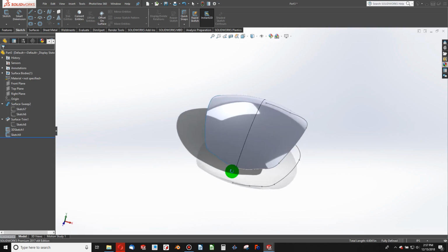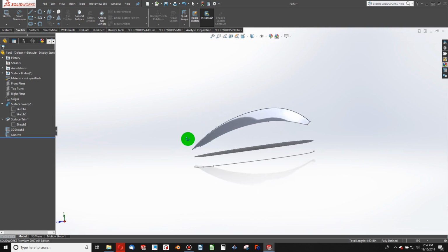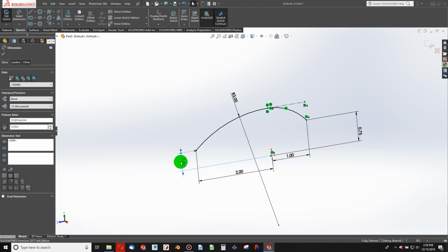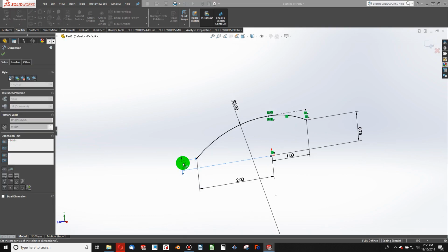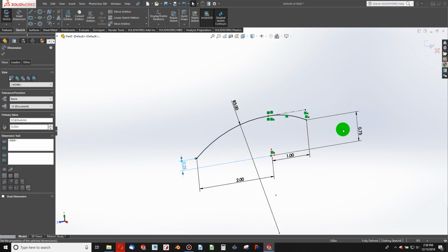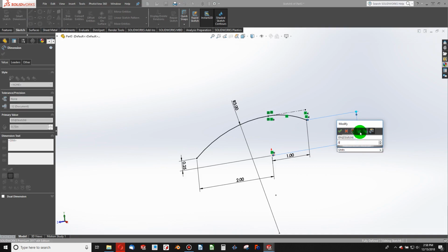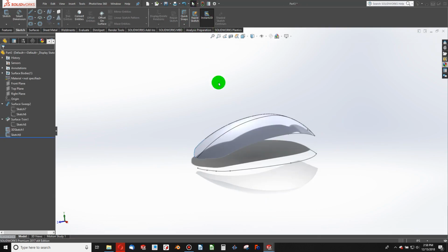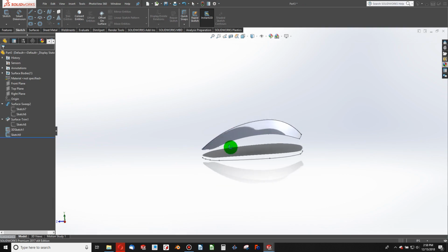And of course, when you start with a wireframe, I think this mouse looks a little bit tall. So I'll go back. The beauty of parametric modeling is I can always make changes. I'll make this dimension come back down to 1/4 inch after all. And I'll make this maybe 1/2 inch. And that seems a little bit more reasonable and computer mouse-like.